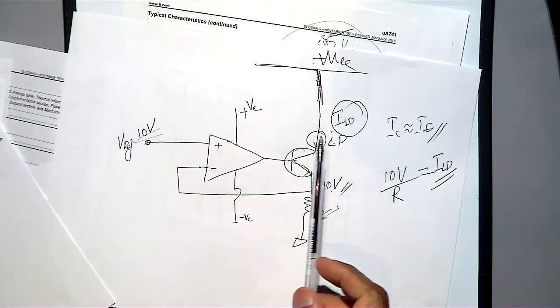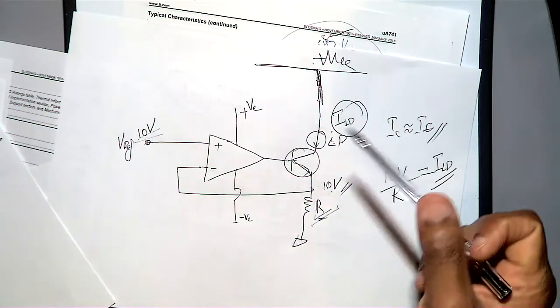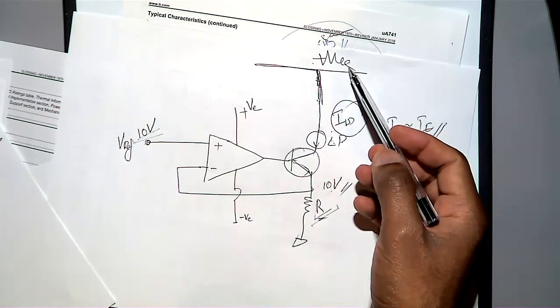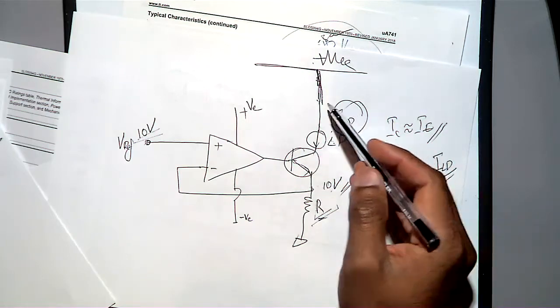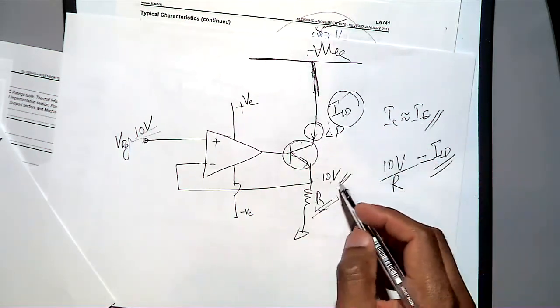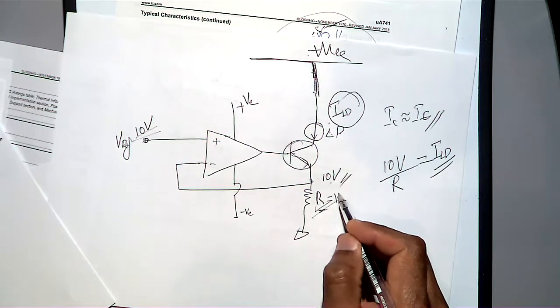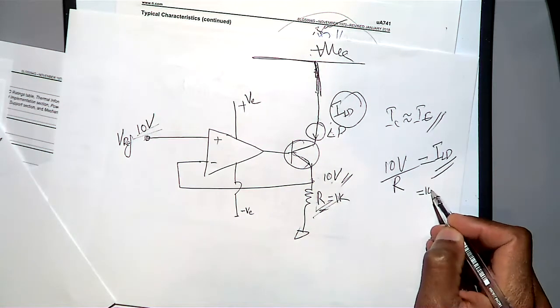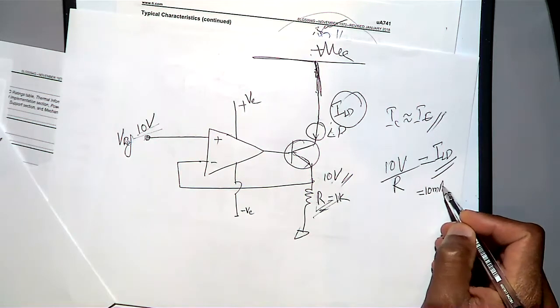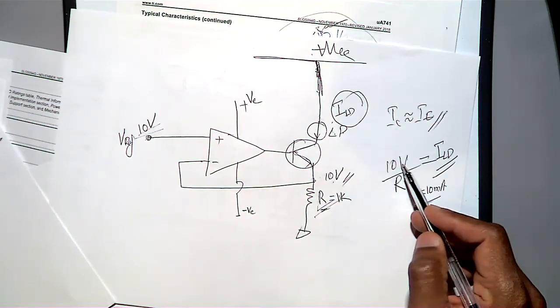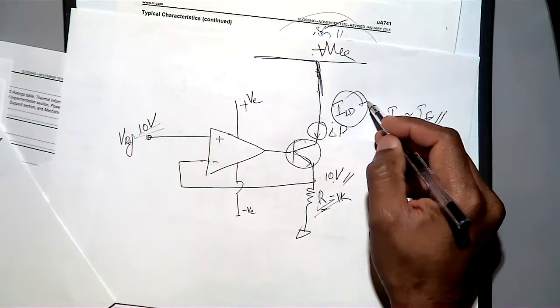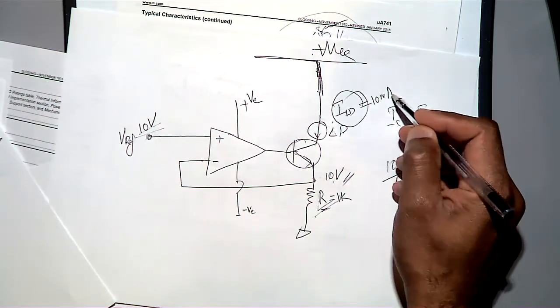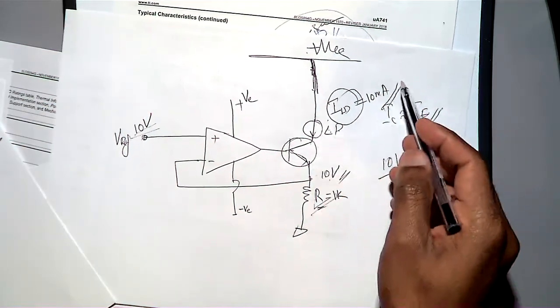Then due to some reason, could be due to power supply or due to temperature, this current, so this current you have set, maybe this R equals 1 kilo ohm. So what is the current? 10 milliamps, because 10 volt divided by 1K. So then that is equal to 10 milliamps is the current flowing through the laser diode, that is a requirement.